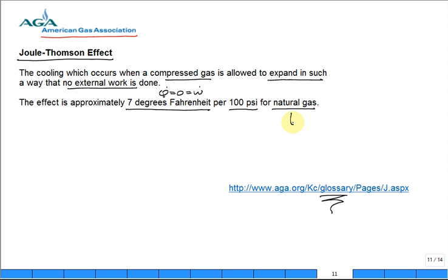So what is natural gas primarily? What component? Methane, CH4. So if you have a pipeline of methane, and there's lots of pipelines of methane, and you have a valve, and that valve is partially closed, it's a restriction. And maybe you come in here with 1100 psi, and it drops down on the back side of the valve to 100 psi. All reasonable pressures. So what's the delta P? It's 1,000 psi pressure drop, right?